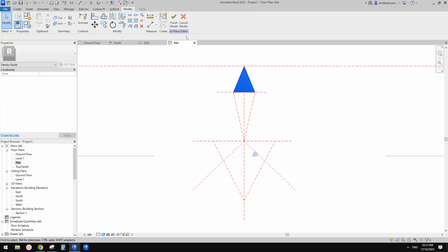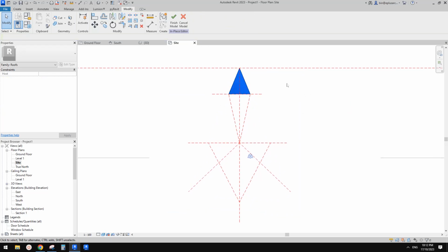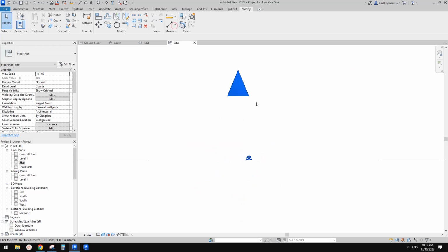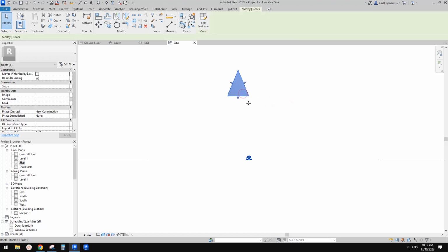And then I'll just, let me think. Yeah, I think I will just finish this model in place, because instead of having multiple voids plus multiple solids together, when you create a void it will automatically cut, and then trying to uncut it will be quite confusing. So I'm going to just model them separately. So now you can see this is one model in place.